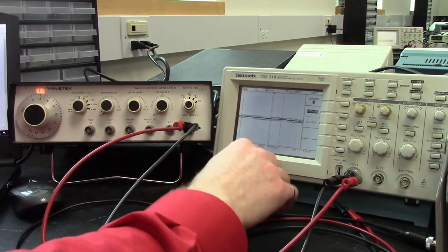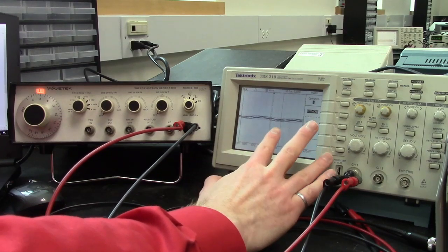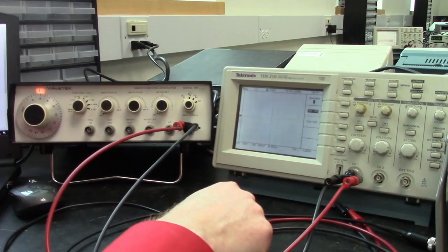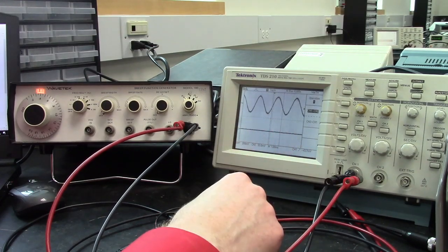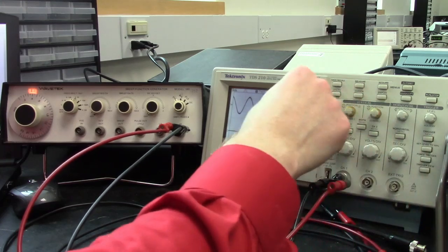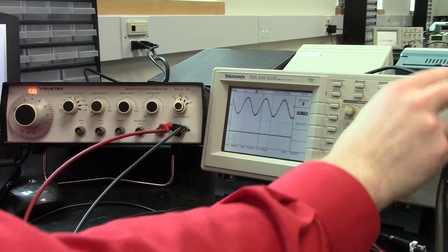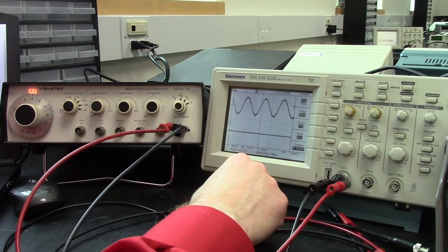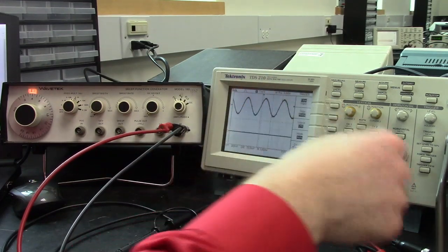So to get the scope to work, if you're ever stuck and have no idea what to do, then your last resort is to just hit the auto set button at the top and hope for the best. But what we really want to do is understand how things are actually working. So the scope goes on a triggering system. What you can do is set the level for where you want the scope to decide, okay, this is the start of a pulse.